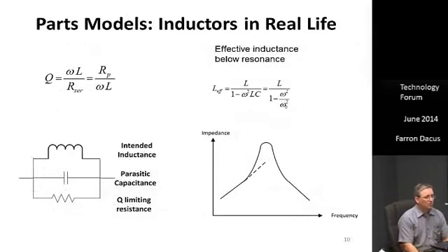Okay, now let's look similarly at inductors. As I said before, capacitors typically show a series mode self-resonance. Inductors are the opposite. They tend to show a parallel mode self-resonance. So if we look at their impedance over frequency, at low frequency it's going up with inductance just like you'd expect, jωL, but then it starts accelerating above that linear line, reaches a peak, self-resonant peak, and starts coming down.